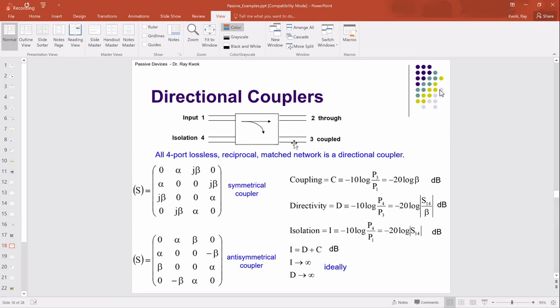A lot of systems will say, okay, if I receive a signal, I will turn on all my power amp, for example. And how do I know I have a signal coming in or my antenna is picking up a signal? Well, I tap this off a coupler, like a 30 dB coupler. 30 dB coupler means I'm only taking 1/1000 of the power, right?